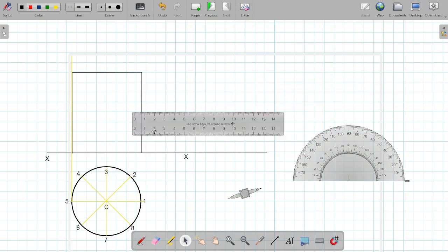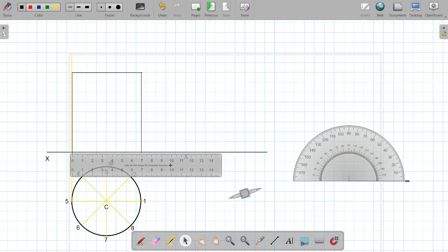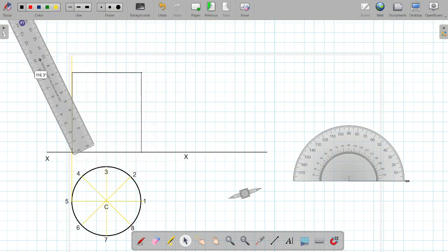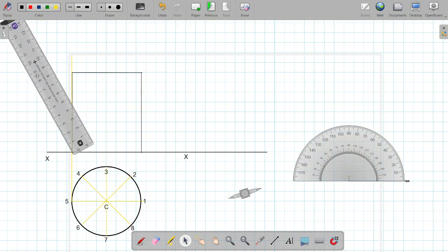For that, we have the technique of parallel lines. So we will keep here the scale, measure any angle theta less than 30 or around 30. Exactly the same procedure that we had followed earlier. Then I will mark 1 centimeter here because of the space constraints. You can also mark 2 but it should be equidistant.